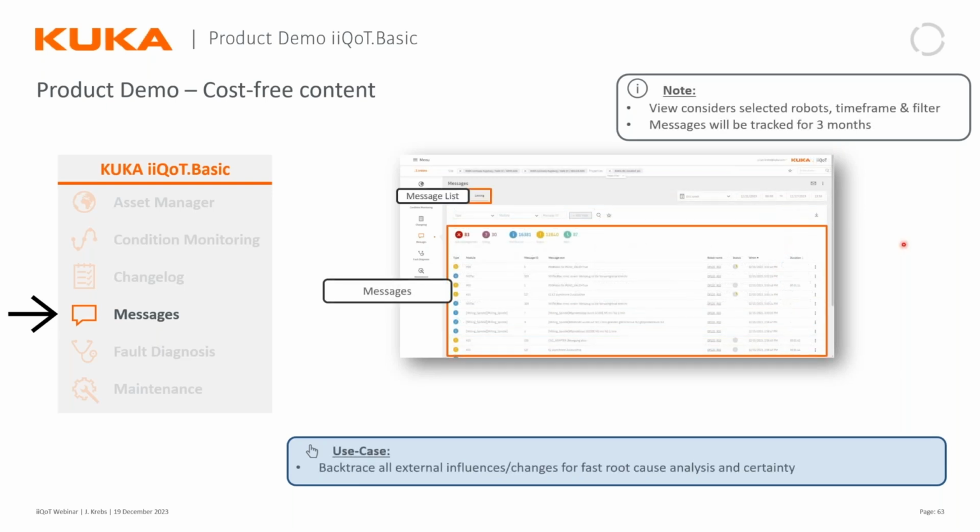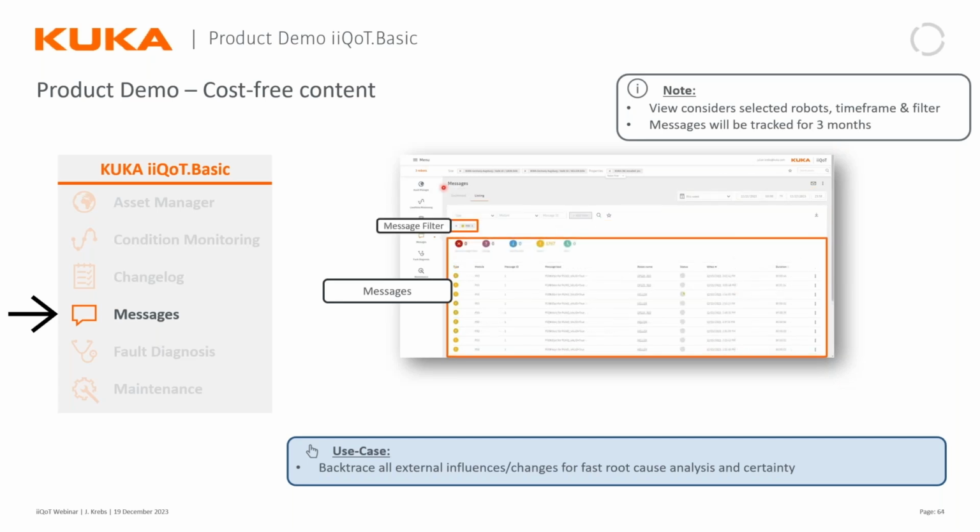The second tab we do have here, besides the KPIs, is the straight message list. That's basically what you see on a SmartPad, top down, newest on top, older ones getting pushed down. Here again, I have my filter functionality. I have again my time frame and my notification rules. And if I put another message filter in there, for example, if I only wanted to see the status messages, well, then it just shows me that.